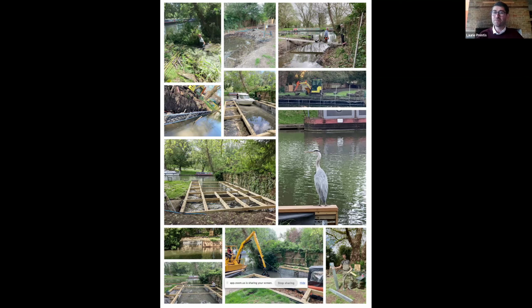The scaffold poles were reclaimed from the scaffolders once they get to a certain age and get to a certain amount of cutting off the end and below about 2.4 meters. They have a habit of being taken to the scrap merchant. So we took those, we knocked them into the ground, we put a jointing beam on them, and kept poking into the ground to approximately 4 meters. There are pairs of them on each different point.